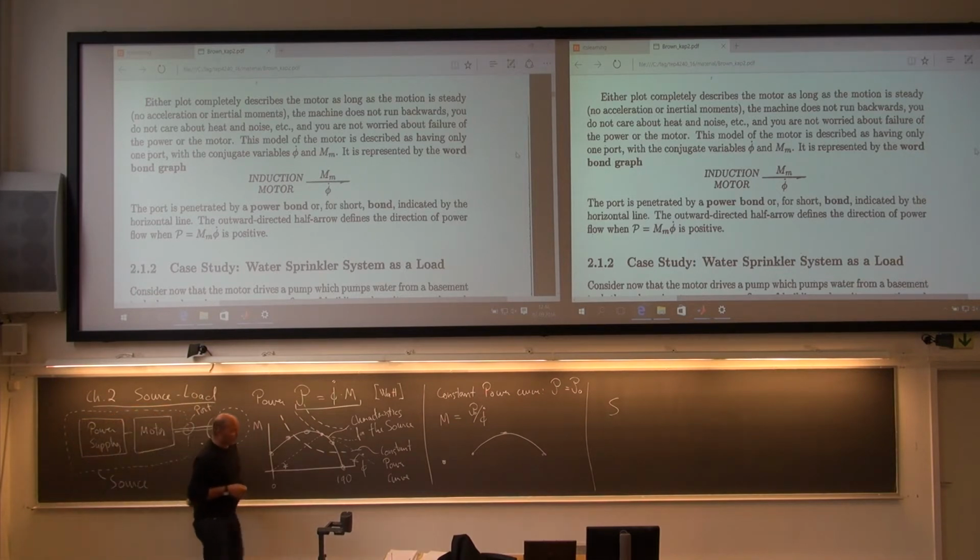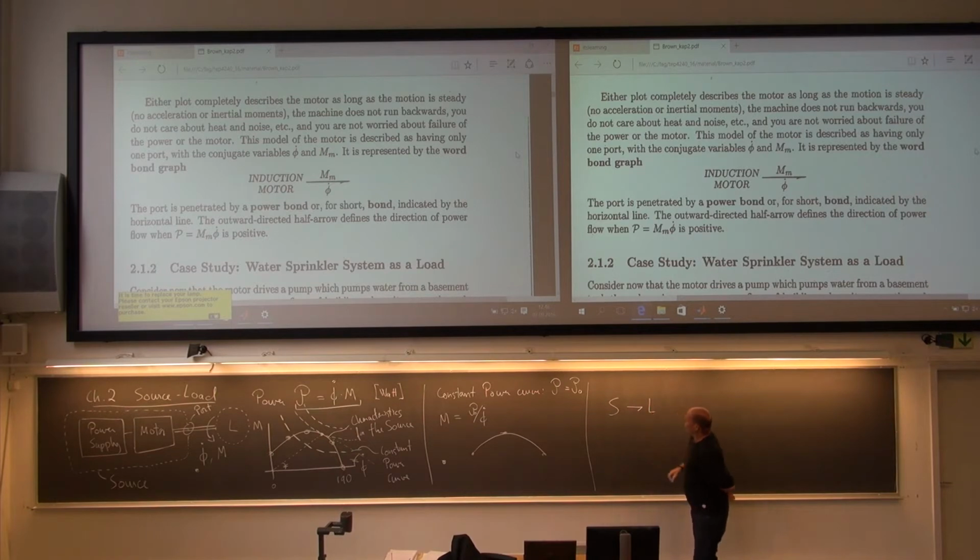And the graphical drawing for this system will now look something like this. That is your first bond graph. So now it represents the power transfer from a source through the ports into the load. We use half arrows, and these half arrows we call a bond.